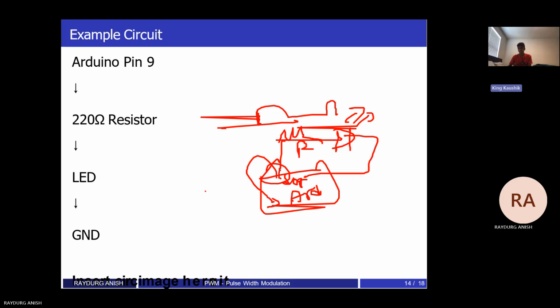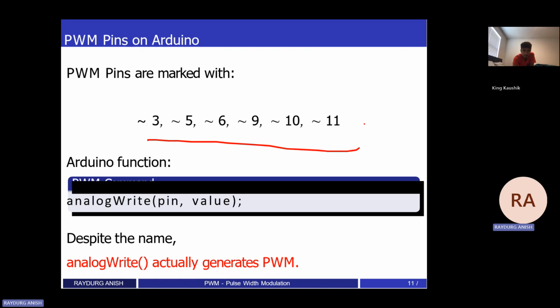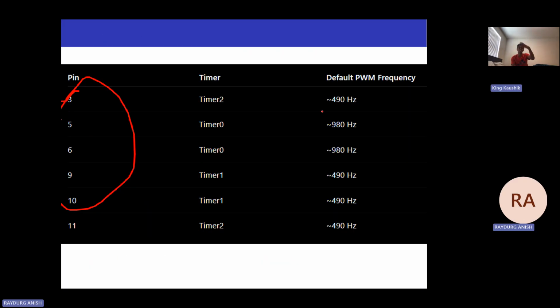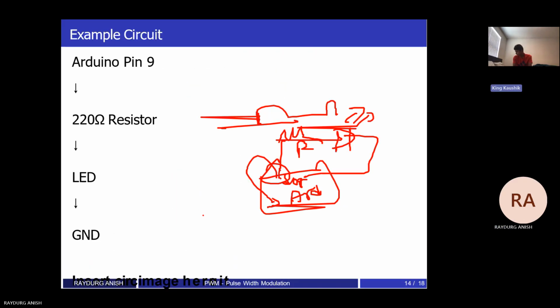So I use the same LED? Yes, use the same LED. These are the analog PWM pins: 3, 5, 6, 9, 10. Just use the same LED which works well, not that RGB LED, which red was very dim.